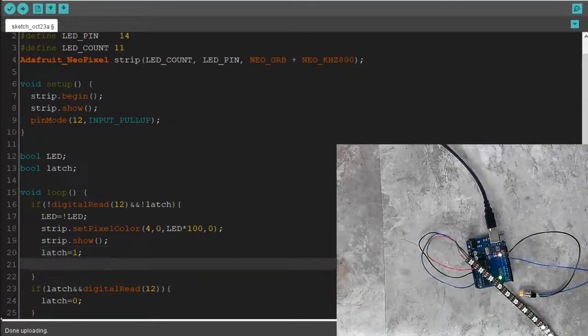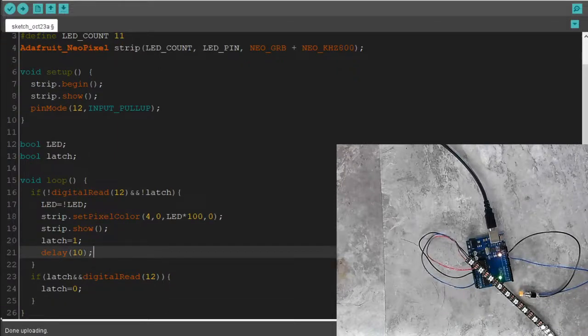So what we're gonna do here to fix that is do a tiny little bit of a delay. We'll do a delay of 10 milliseconds. And that's overkill, but it works. As humans, we're not going to have an issue there. Because unless we can touch this thing faster than 20 milliseconds, it's not going to be an issue. What is that? 50 times a second? Yeah, that's pretty fast. That's like subwoofer frequency. That's faster than the bass note on a bass guitar oscillates. Okay, so upload that and let's see if we're steady now.